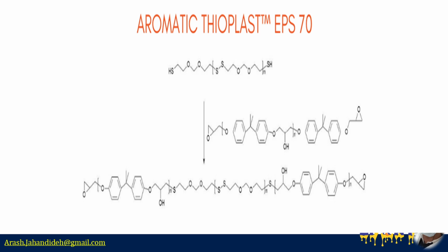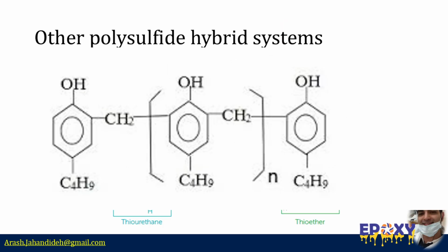At elevated temperature, phenolic resin reacts with stoichiometrically added liquid polysulfides through a polycondensation reaction, releasing water as a byproduct. The resulting material can be viewed as a block copolymer where the rigid phenolic segments are combined with flexible polysulfide chains. This structure produces adhesives characterized by high flexibility, impact strength, chemical resistance, and strong adhesion to various substrates.